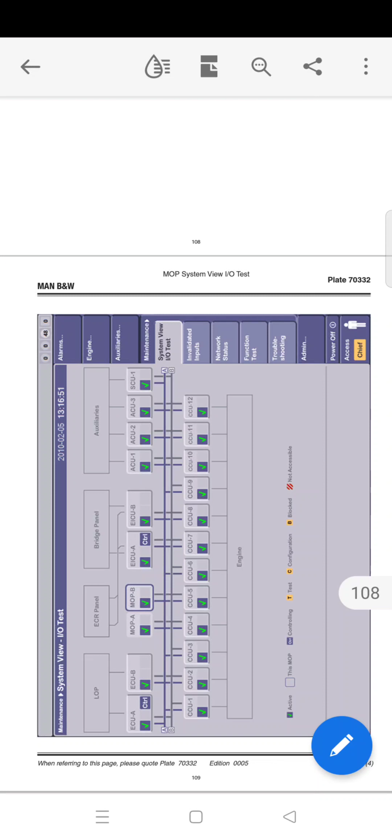So it includes an on-chip timing coprocessor for synchronization with the crankshaft rotation and speed measurement. To ease the production of the multi-purpose controller, all programmable components are in-circuit programmable, which also allowed field update of the controller by means of relatively simple tools.